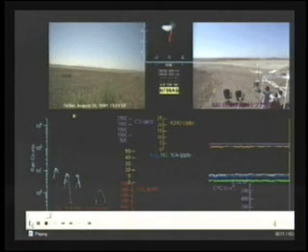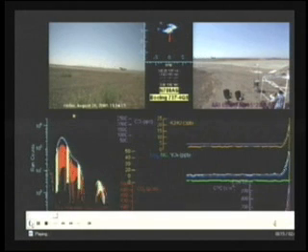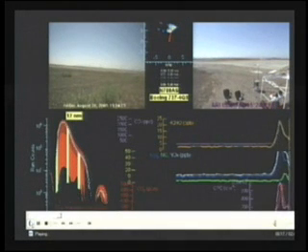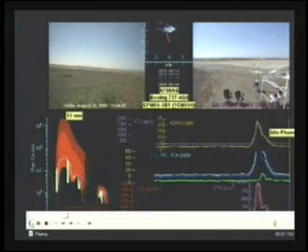Takes a little while for the wind to carry the exhaust by. We grab the tail number off of that, so we know it's going to be a CFM56 engine. The emissions come. We see it peaked at high particles. You see a shoulder over there that's associated with the soot, but it's really dominated by the small particles in that case. We can compare the gas phase measurements that we made, because we know what engine we're looking at, to the certification values for that airplane, and can look at the hydrocarbon emissions, the carbon monoxide, and the NOx.